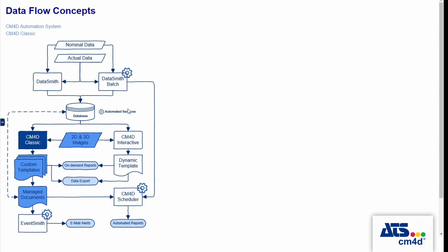So related to Datasmith is a module called Datasmith Batch. This is set up on an application server that the software can be installed on, and allows an administrator to create parameters for the batch mode for Datasmith for loading data. So typically, setup tells the system where to look for files and how often, which types of files to load, which translators to use, and what to do with the files or where to store them after the processing has happened.